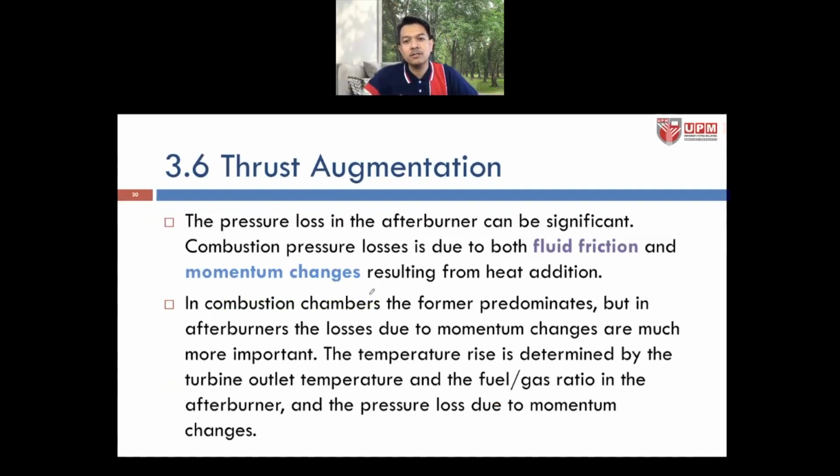Combustion pressure losses are due to both the fluid friction as well as the momentum changes resulting from the heat addition. In combustion chambers, the former, which is the fluid friction, predominates, but in afterburners, the losses due to the momentum changes are much more important.